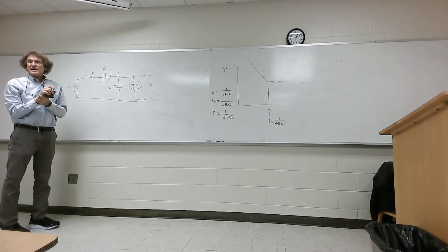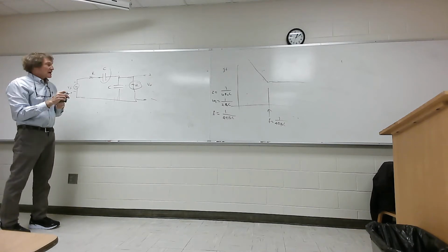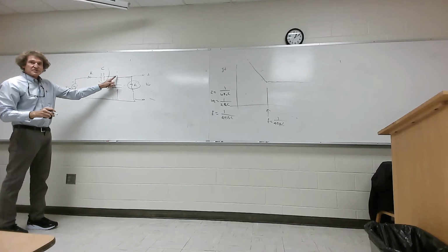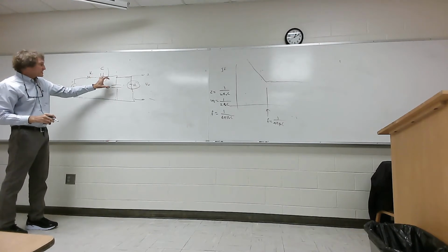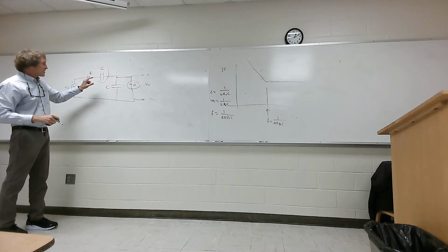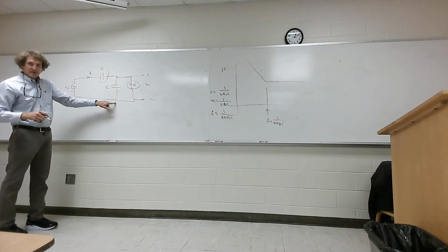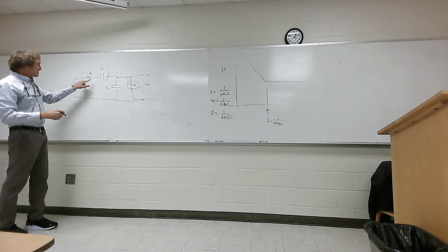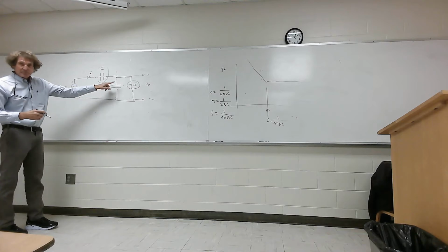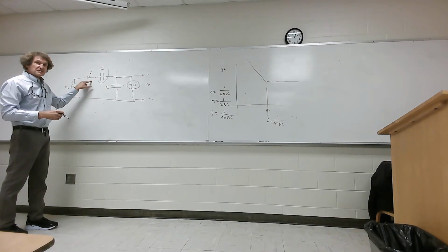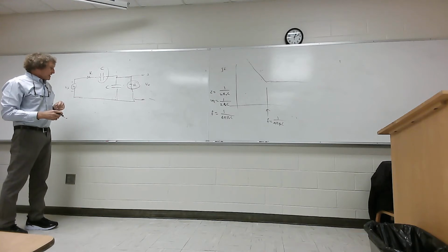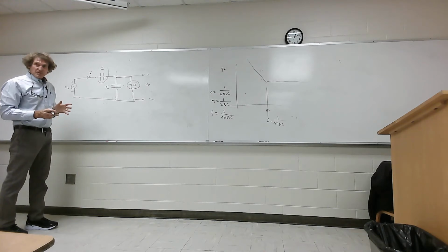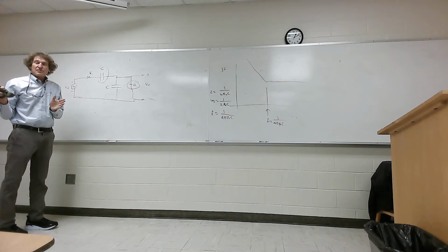All right. What is it at high frequencies? Well, at high frequencies, this looks like a short, but so does this, right? What it really amounts to is you're going to get voltage division between these two capacitors. Really, whatever the voltage is here, half of it will be here, at very high frequencies, right? But that voltage is going to be brought down by the fact that resistance doesn't change, and the net impedance here is going down. So you take a look at this. It is a type of bandpass filter, but it's not something you're familiar with.